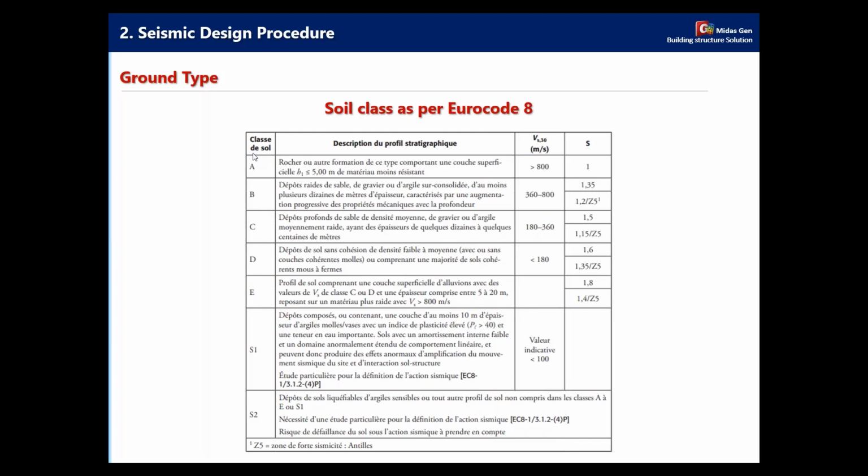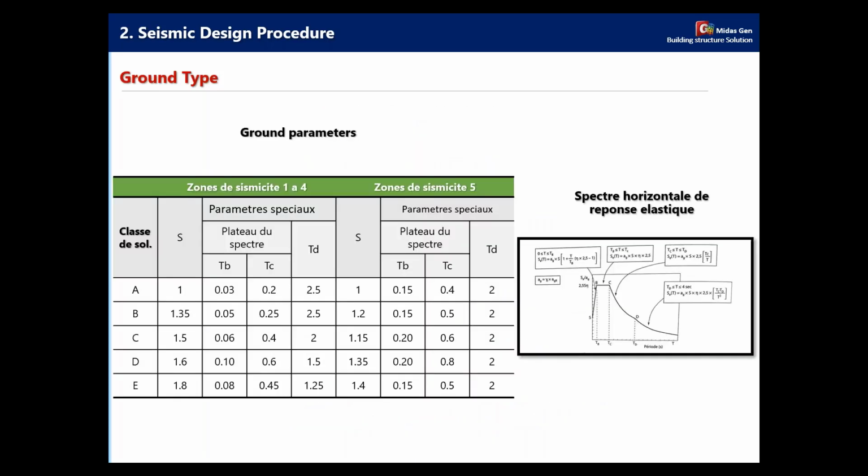These are the speed of the wave of the seismic force, and this is the geological amplification coefficient that is represented in this column. After you select the soil, you also need to define the periods of the response spectrum. As you can see here, there are 4 points. We can find them when we have the data for the earthquake. After getting the data of the earthquake, we can identify these points as B, C, and D.